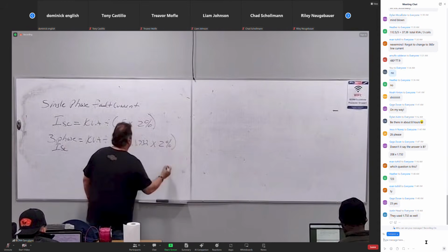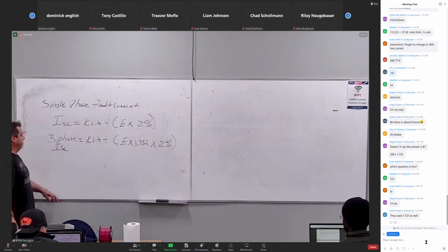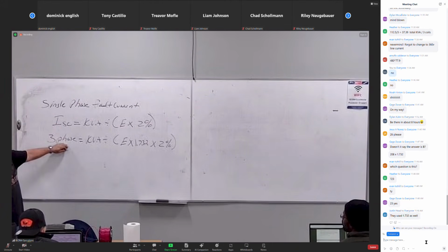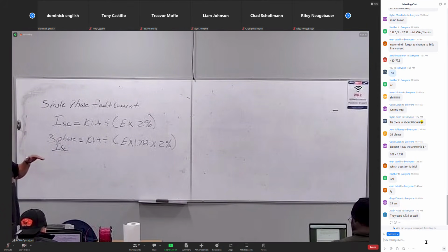Okay, those are the two formulas, my bad, I apologize. Single phase fault current: no 1.732. Make sure you look at the system, not what faulted. Three phase fault current, 1.732, that's going to change our answer, isn't it? It should, because when we multiply by 1.732, we increase that voltage, and that percentage is going to change. Now we have a higher voltage into the same KVA, and so the answer will be less.